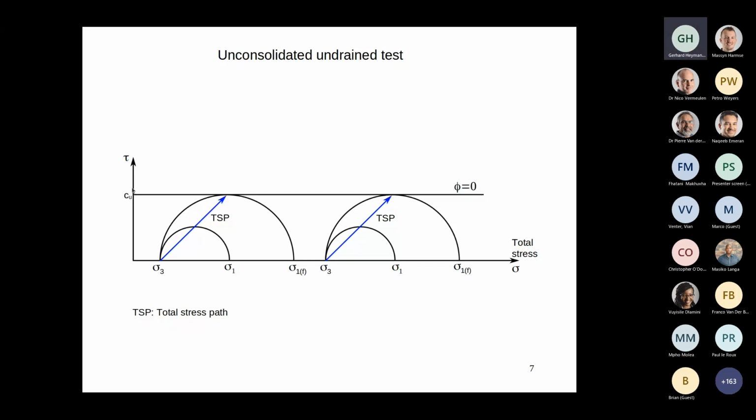The crudest of all in situ tests is what? The SPT, yes. And then we have the DPSH, the second crudest. And then we have the CPT. And then we have the CPTU. And then we have the vane shear test, which was specifically designed for that. So if you really want this number, this unconsolidated undrained shear strength, rather do an in situ test. Your chances of being successful are much, much better.